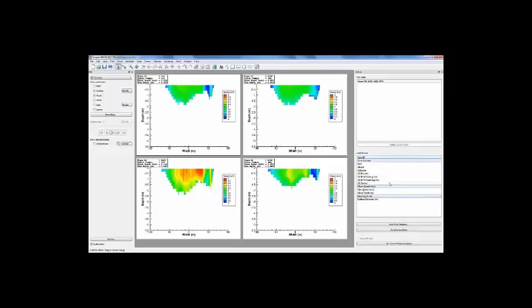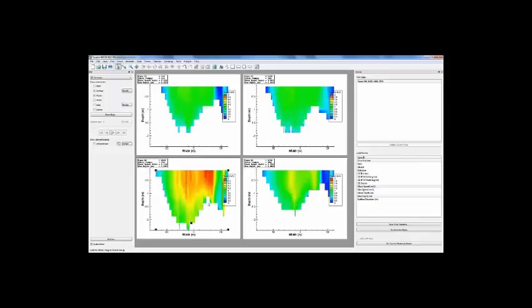We're always looking for what are the dynamics of my system? How does this change? Being able to look here at whatever flow events we've done the calculations for, immediately comes to mind something like model calibration. Being able to look at multiple flow events, and look at my behavior throughout a cross-section, a cube or a reach, and now among different events, allows me a lot of power to calibrate my model, to validate, to say here's the kind of errors and uncertainties in my model results.